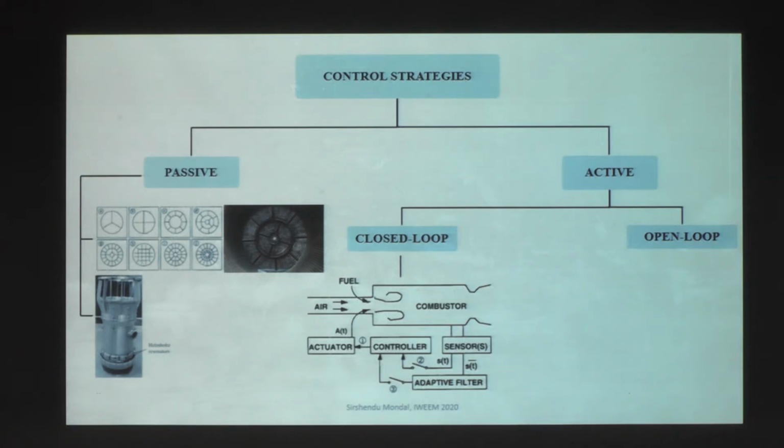On the other hand, open loop control also uses forcing or external excitation, but at a frequency which is non-resonant, away from the thermoacoustic instability frequency, and there is no real-time feedback. Thereby the design of such strategies is cheaper and easier.